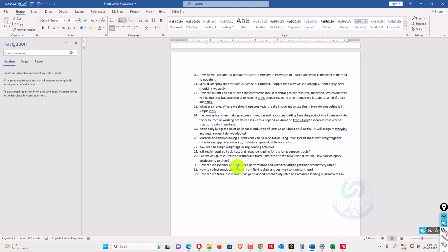In the daily progress report there should be some quantity of work written. It should be specific, and the shop drawings should be given on the site, and also the QS should be involved. He should, before the project, divide and distribute the quantities of the project, and after doing the work, you should know how much quantity of work has been done.